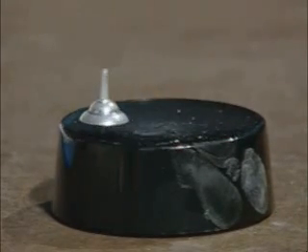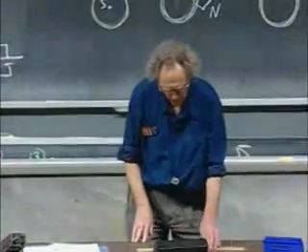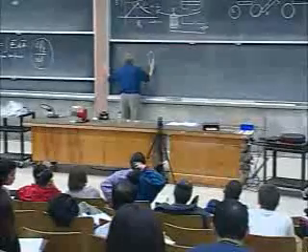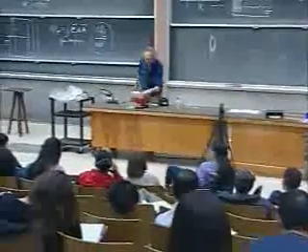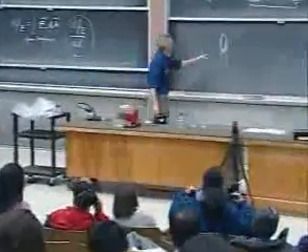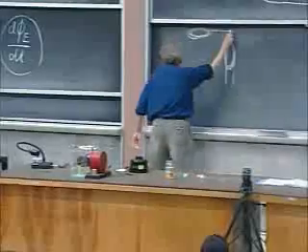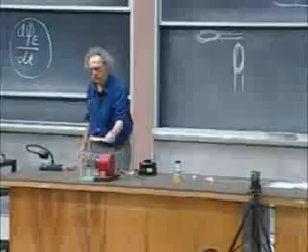I have another fantastic toy for you, which is also an induction motor. And that one you're going to see there. I first want to explain to you how that one works. That's a real beauty. It is an induction motor that runs on a two-phase current. Here we have a solenoid. It's this baby here, big one. And we're going to run 60 Hertz AC current through there. And here we have one, also going to run 60 Hertz AC through there. Here's the coil. This one is easy to show. The other one, very heavy.